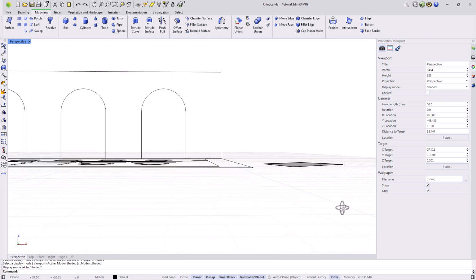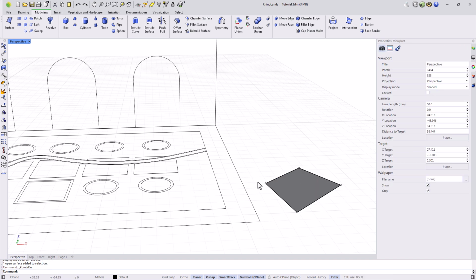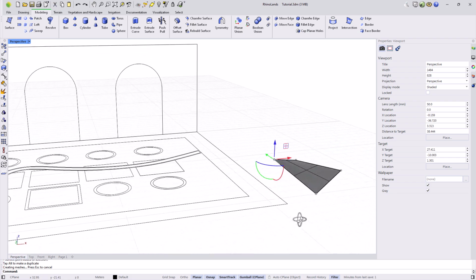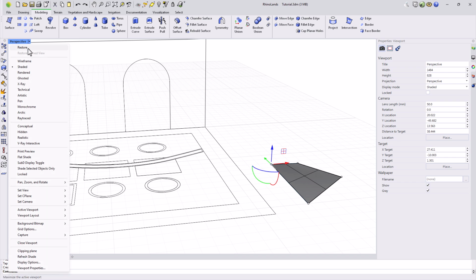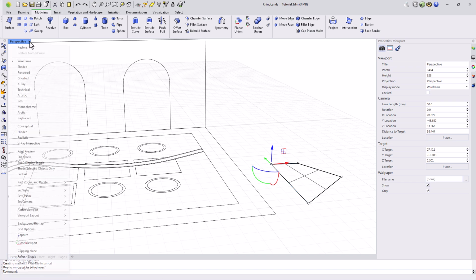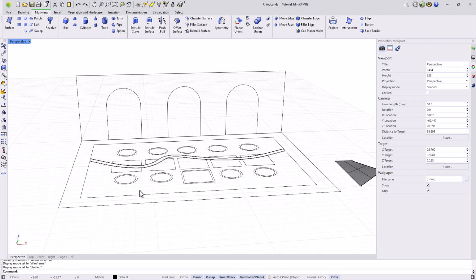By default, it projects onto the construction plane, creating a flat surface, and we can also activate its control points, which correspond to the vertices, and move them in space, so I can turn this flat surface into a 3-dimensional surface. To see it this way, we have the viewport in shaded mode. If we work in wireframe, what we'll see is this face represented with its wireframe structure.